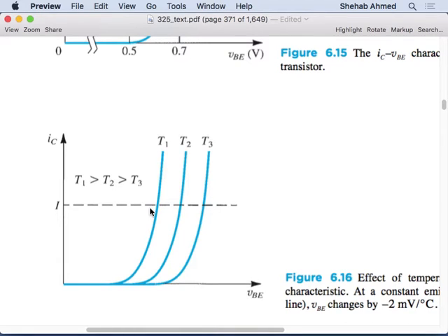One thing to note is, again, when the temperature increases, the voltage across the device decreases, right? It's called a negative temperature coefficient device. This makes it a bit more challenging to put devices in parallel, because when you put devices in parallel, you want to make sure that they share the current, right? So what happens when a device has more current than the other? It should get hot. If it gets hot, what do you want it to do? Theoretically, you want it to resist more current, right?